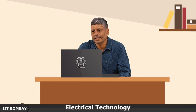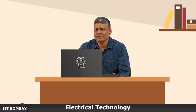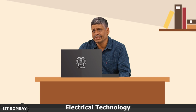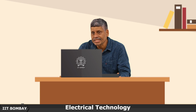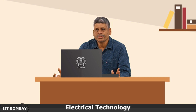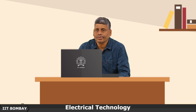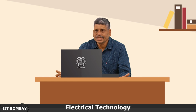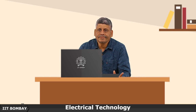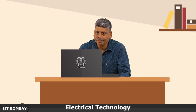But now we will again revert back to the physics, through the method of co-energy that we have been practicing. Right at the very basic level, we have 6 coils, 3 on the stator, 3 on the rotor, and they are mutually coupled. Because the rotor coil can rotate, some of the mutual inductances will be a function of theta, and we will derive the flux linkages associated with these coils as step number 1.